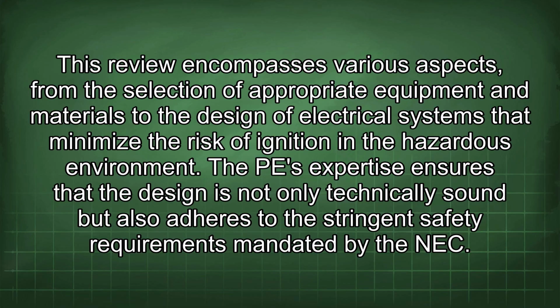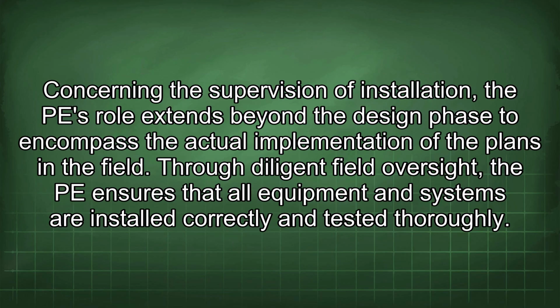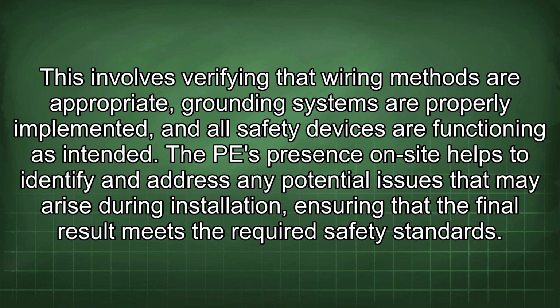The PE's expertise ensures that the design is not only technically sound, but also adheres to the stringent safety requirements mandated by the NEC. Concerning the supervision of installation, the PE's role extends beyond the design phase to encompass the actual implementation of the plans in the field. Through diligent field oversight, the PE ensures that all equipment and systems are installed correctly and tested thoroughly. This involves verifying that wiring methods are appropriate, grounding systems are properly implemented, and all safety devices are functioning as intended. The PE's presence on site helps to identify and address any potential issues that may arise during installation, ensuring that the final result meets the required safety standards.